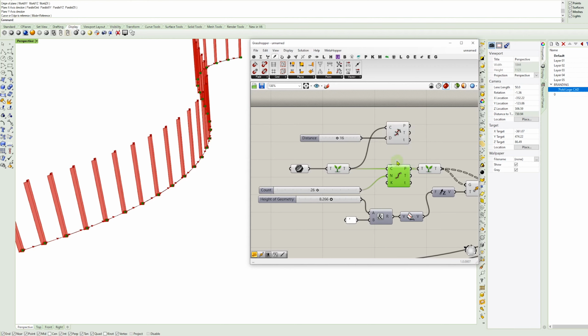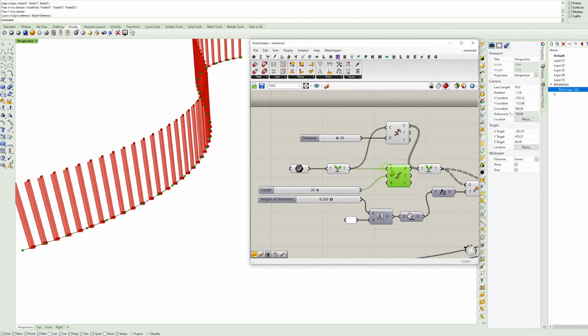So what we can do is if we take that and if we switch, okay, so we have divided distance. We're going to switch that from number of divisions to a specified distance. And you can already see there's a bunch of points happening. But all we're going to do is change that component, and we're going to take the point output and swap that in. And right away, we can already see how that's changing.